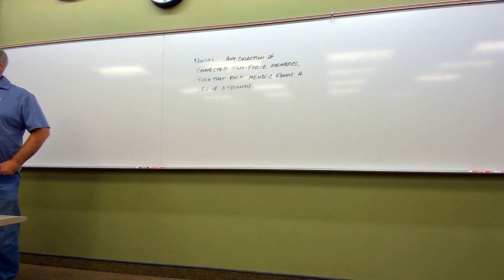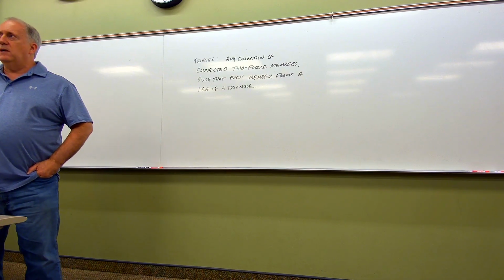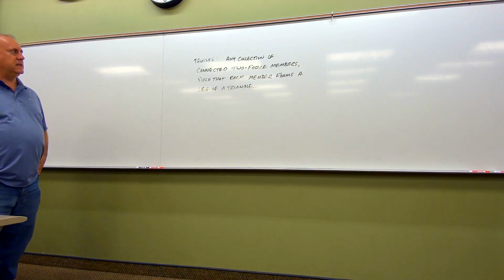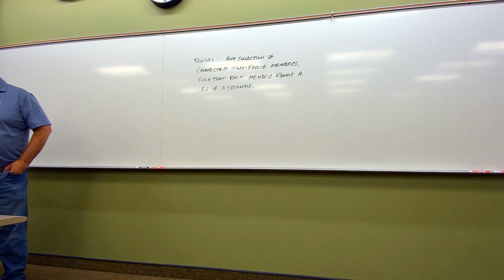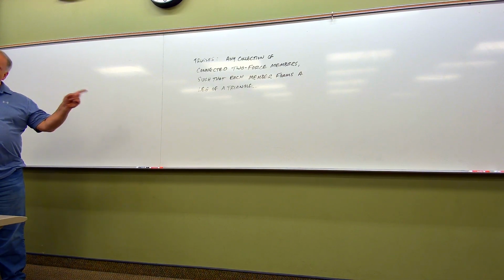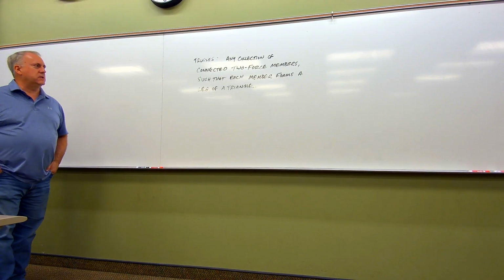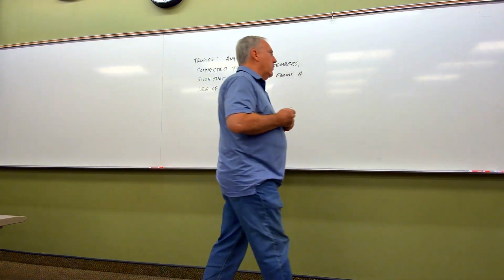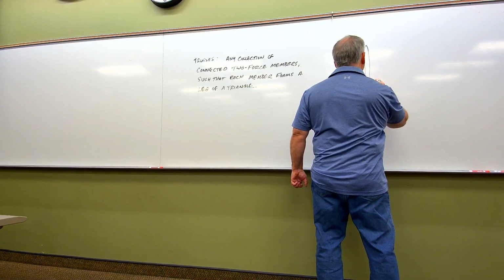Trusses. There's a definition that I put up on the board here, folks, and I want you to know I just spontaneously wrote this. This doesn't come out of any book or anything like that, but if I had to say to you, hey, what exactly, or how would I describe a truss in one sentence, that one there does it. It's any collection of connected two-force members such that each member forms a leg of a triangle. So, for example, if I had a two-force member that looked like this.